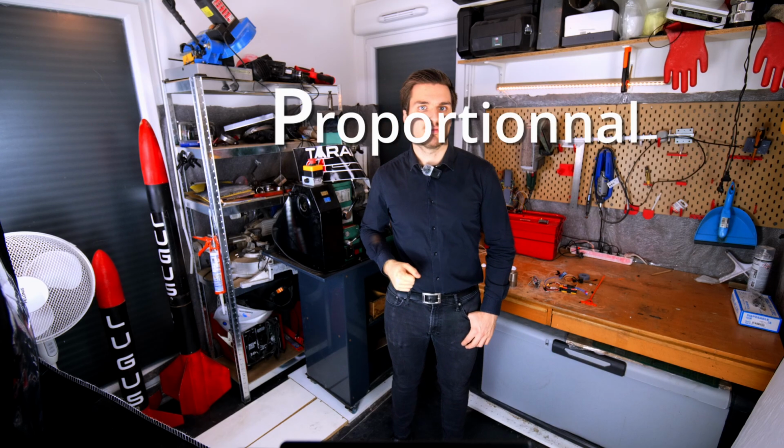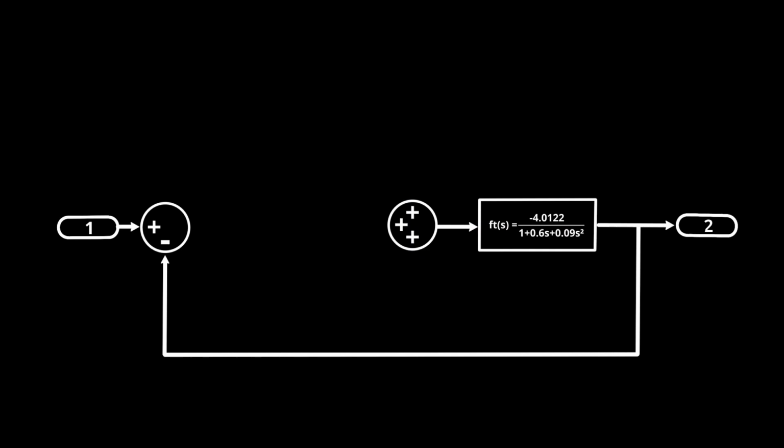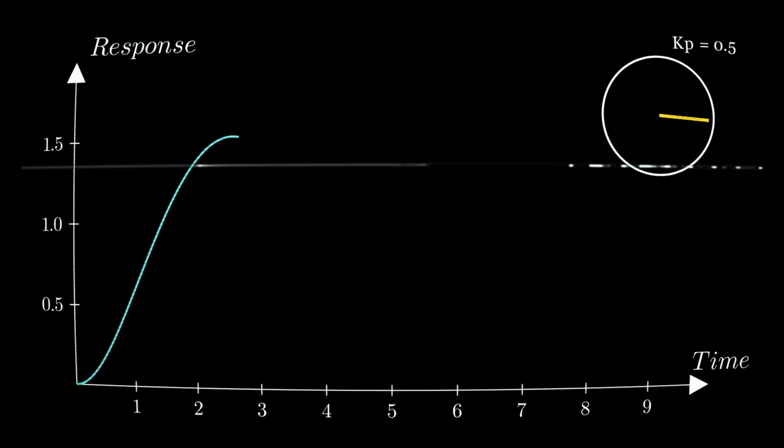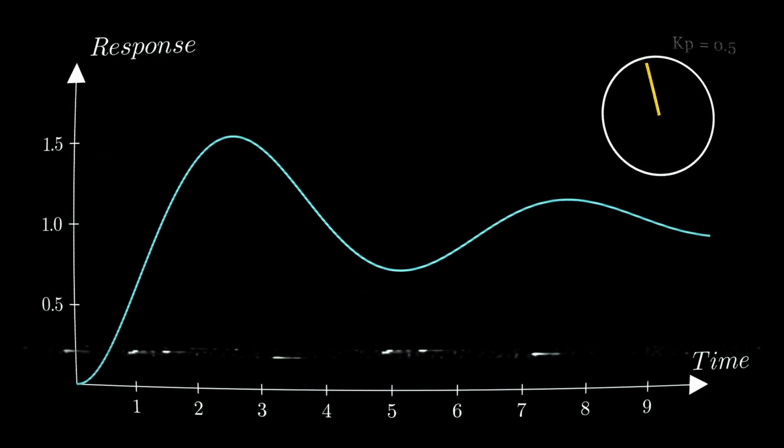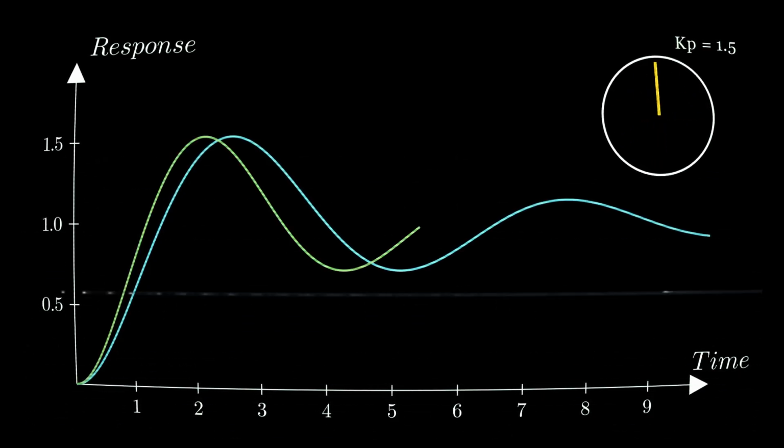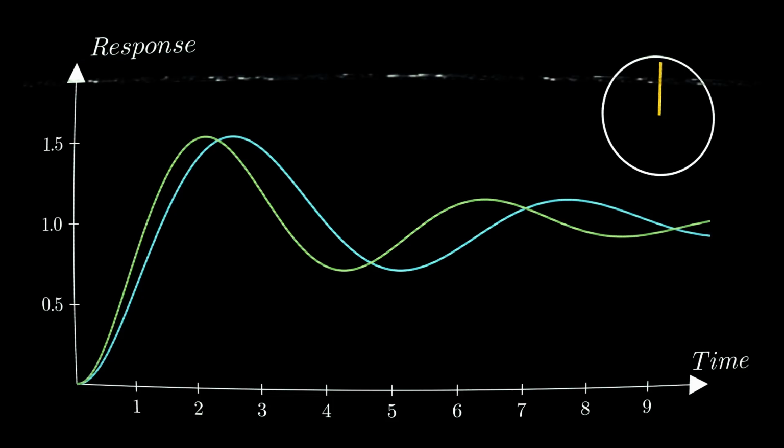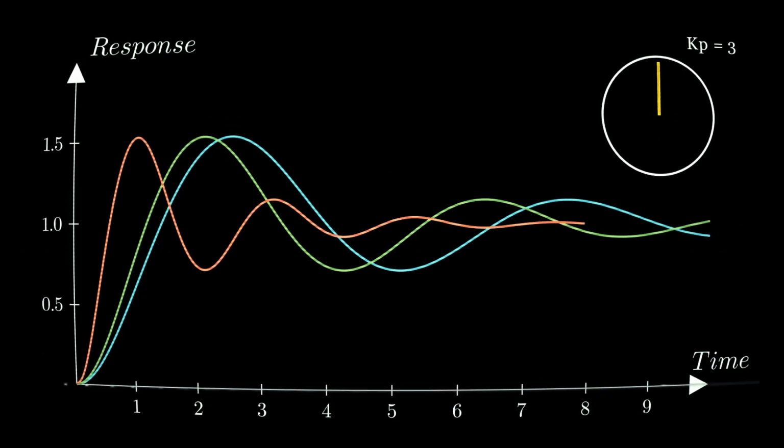The proportional part of the controller is very simple. We take the error, we multiply it with a constant k, and we apply it as a command for the motor. With the right k value, this will work. But the problem is that we tend to overshoot the value well before returning to it. And we eventually stabilize, but not very quickly. Okay, I will need to explain a bit.